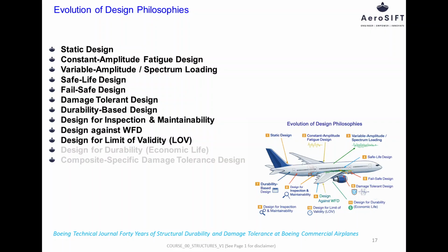Design for durability focuses on ensuring that aircraft structures can withstand fatigue, corrosion, and environmental effects over long service periods with manageable maintenance requirements. This philosophy supports safe operation while controlling maintenance escalation as the aircraft ages. It integrates material selection, corrosion prevention, and service feedback to sustain both safety and economic efficiency.